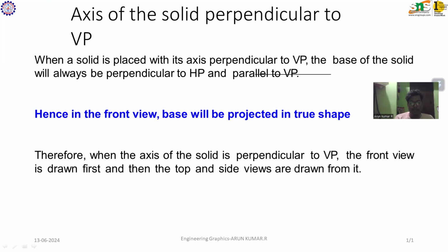The foremost thing we have to notice in every numerical problem is whether the axis is perpendicular to VP, parallel to VP, perpendicular to HP, or parallel to HP. These are the terms used in numerical problems. You have to be clear about which term to use, either VP or HP, while solving problems based on projection of solids. You have to understand these terms and concepts. Once you understand the conditions given in the numerical problem,